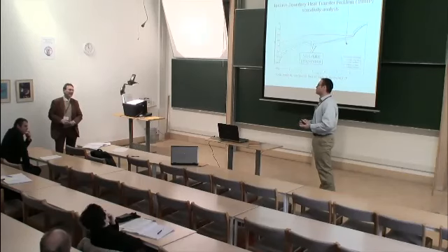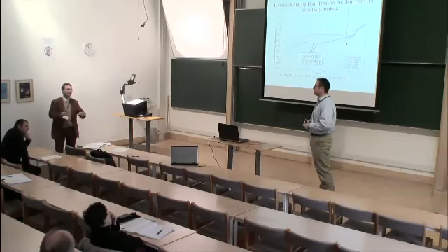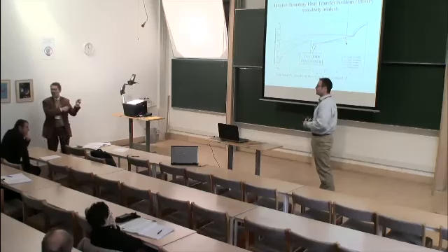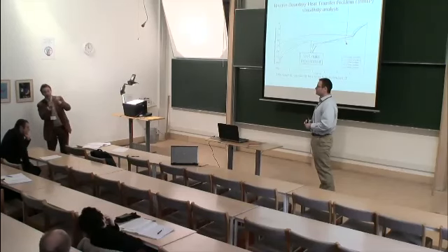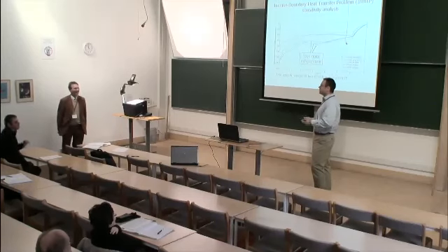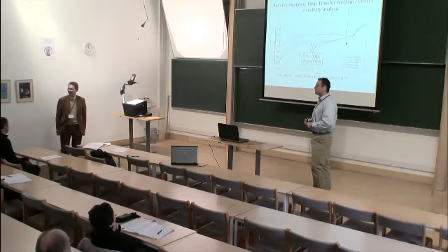It is also a parabolic PDE, so you can set it up in COMSOL like a heat transfer problem or a fluid flow problem. So you set up the adjoint equation analytically and then solve it in COMSOL. Weather forecasting people do it that way, whereas the oil people discretize it and then work out the adjoint. Then I enter it in the console, save it in the file, and then I can take my data as I want. This is how I do it.